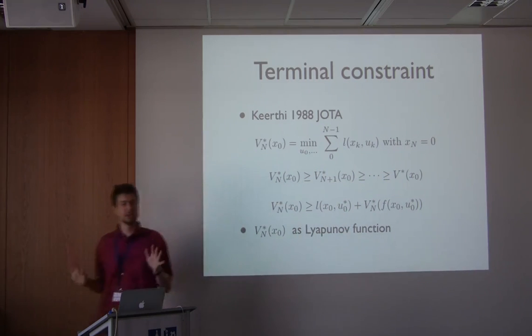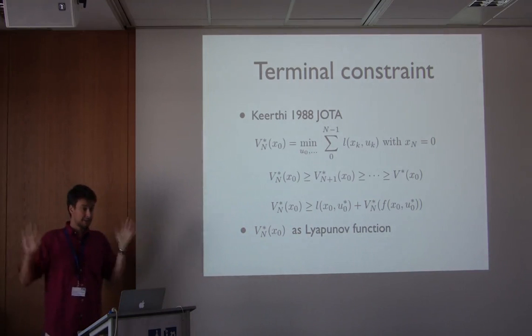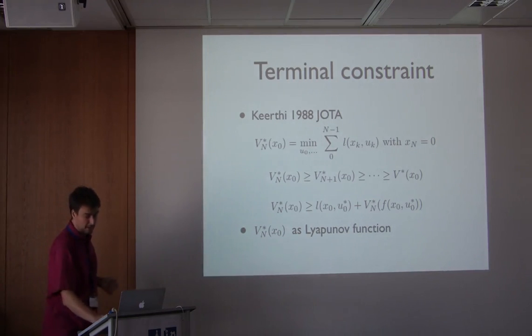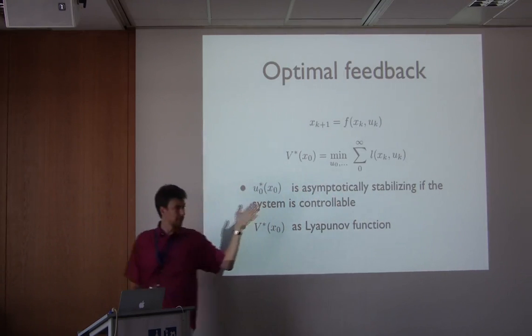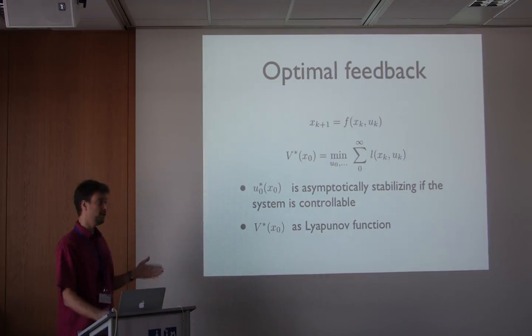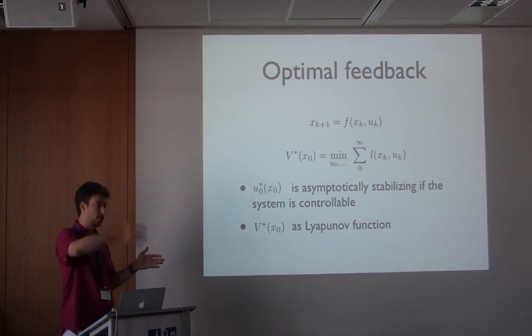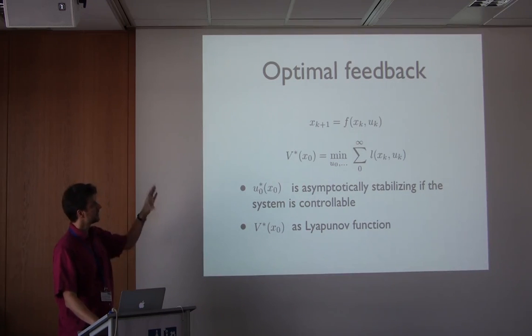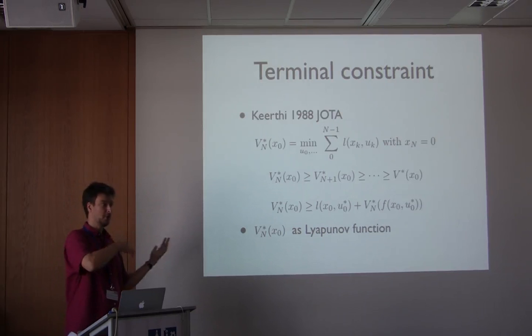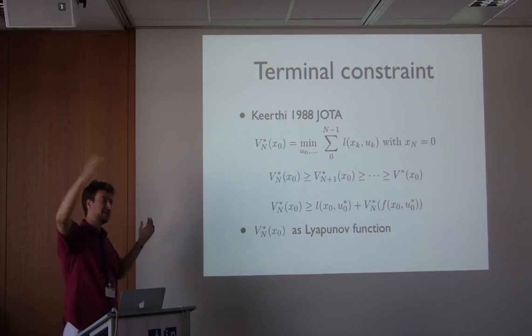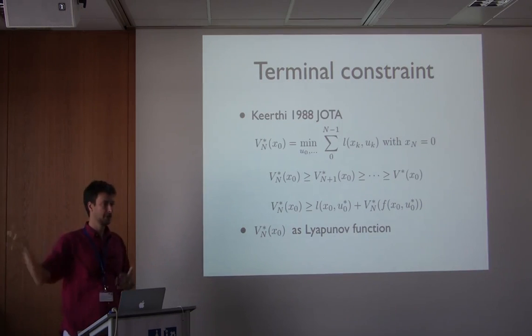And here you can see the connection between viability and capturability. In viability, we're considering the infinite integral. But with capturability, it was proposed that maybe you consider a finite motion, but you impose that you stop after those 2 or 3 steps. So in fact, this switch between optimal control and model predictive control corresponds to the switch between potentially infinite viable motions and capturable motions.